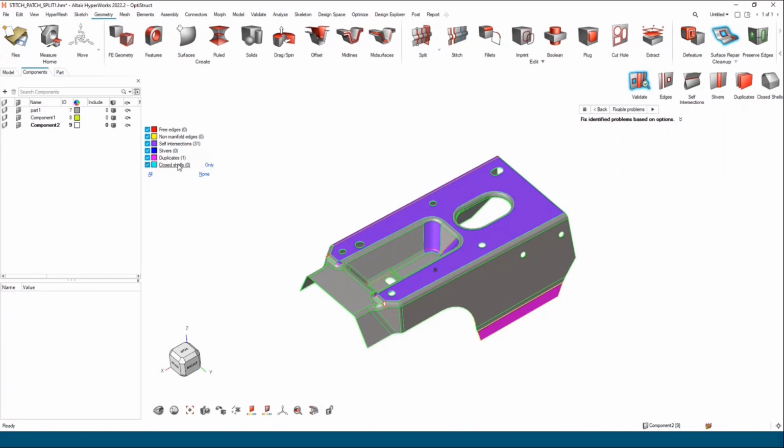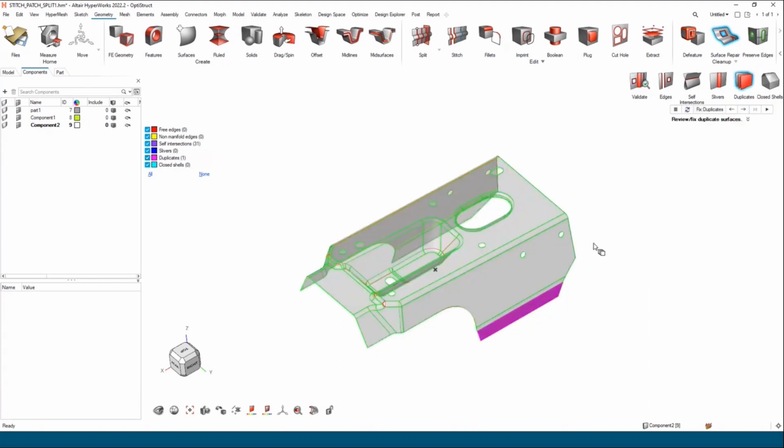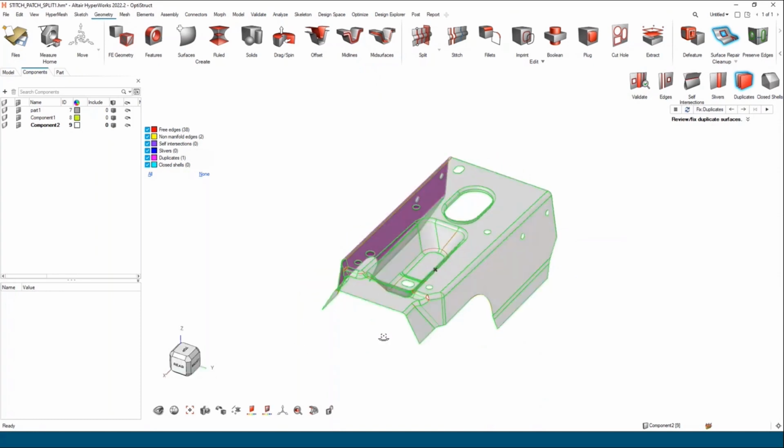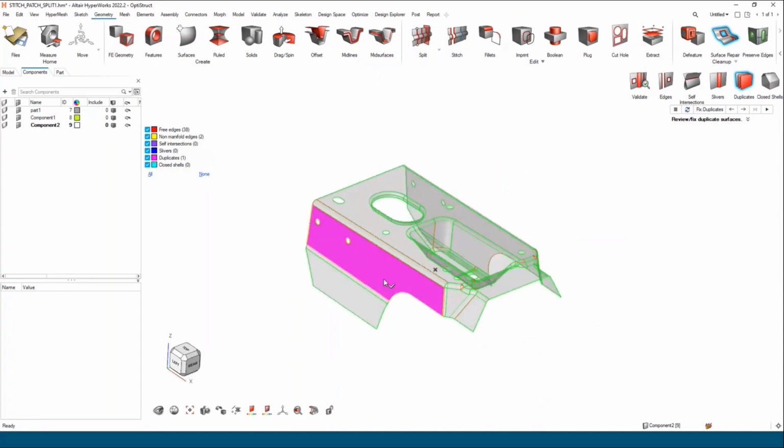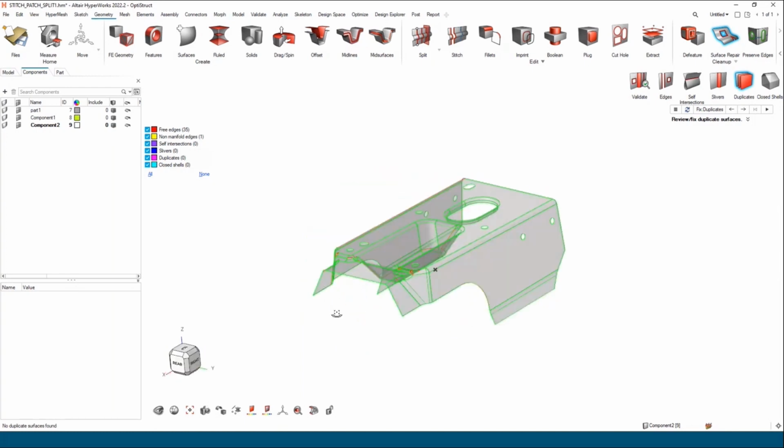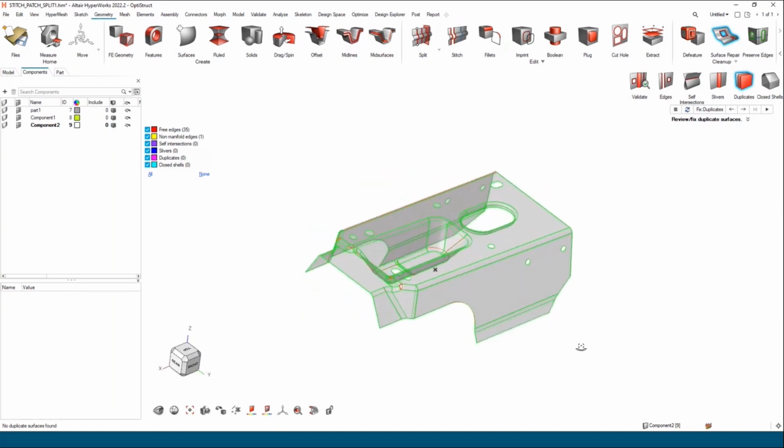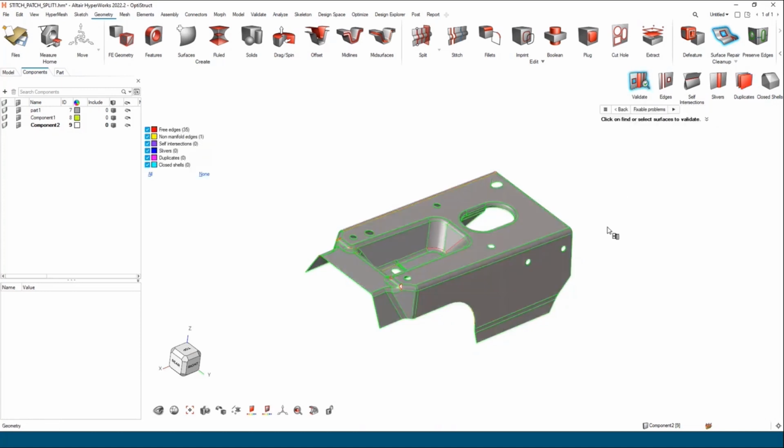So in this particular case, if I click on duplicates, it takes me to this particular secondary tool. I can either go through the model tool, or since there are only two, I can quickly handle this. Again, for this duplicate surface, one of the surfaces would be removed. And as you can notice now, there are no self intersections, right? It has also fixed some of the self intersections, but now it is also highlighted with a lot of the free edges that it has identified.